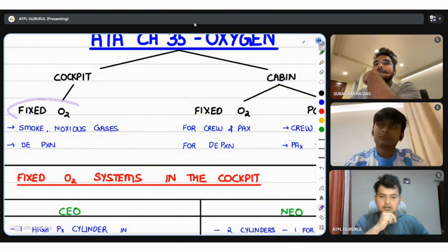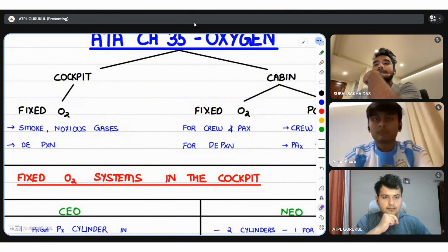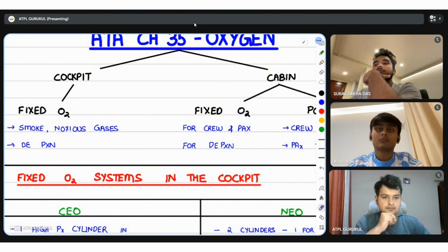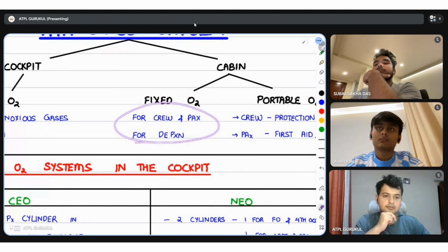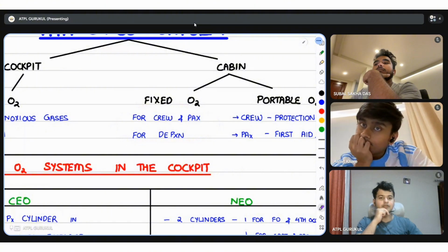However, the oxygen for the flight crew is from stored oxygen in the oxygen bottles. And it's pressurized oxygen from the cylinders. Hence, because it is pressurized oxygen, you can wear a mask which will completely cover your eyes, seal your nose, seal your mouth, and you can directly breathe. Okay? But this is not so for the case of passengers and crew. If there is actually smoke in the cabin, then you, in fact, should not be using that mask because you'll be breathing more of the smoke.